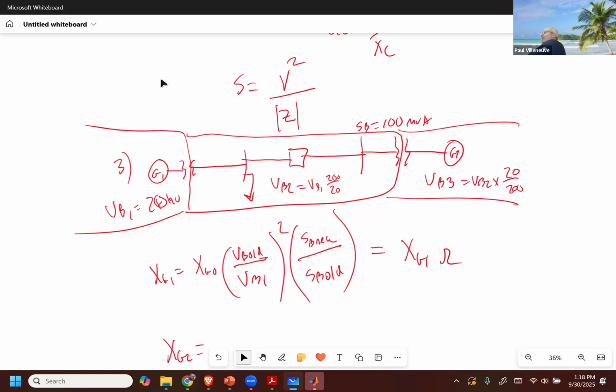And if you look back at one of the labs, we talked about how to do that in the per unit lab. You had a couple options. Do you ever do a per unit with voltage? Yeah, all the time. The VB1 and VB2 we did on the first problem almost never would be written as those voltages. It would be 1.03 at an angle of 22 per unit voltage.